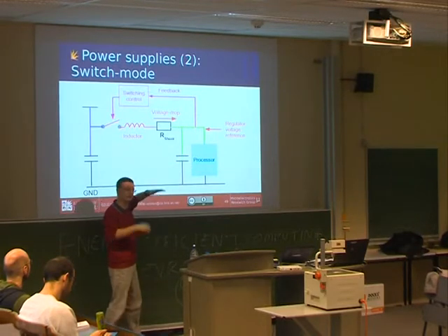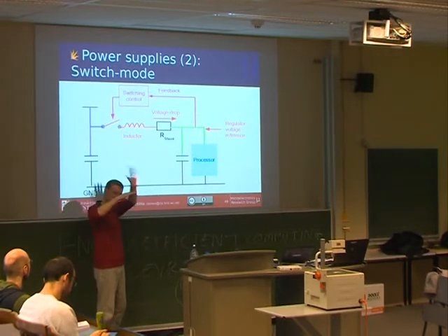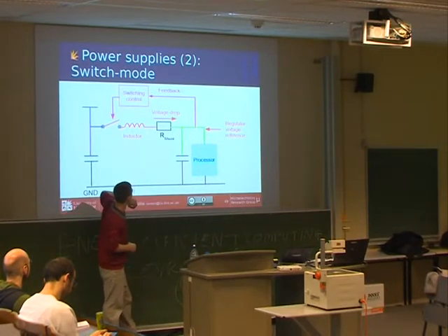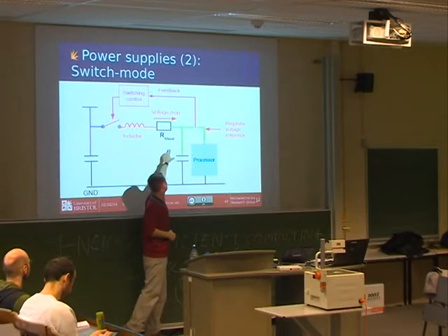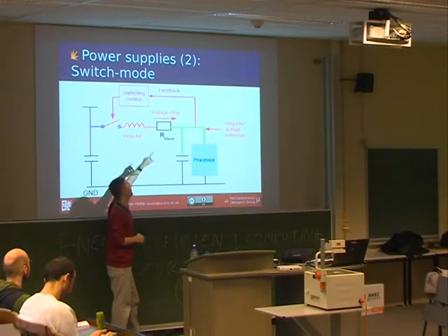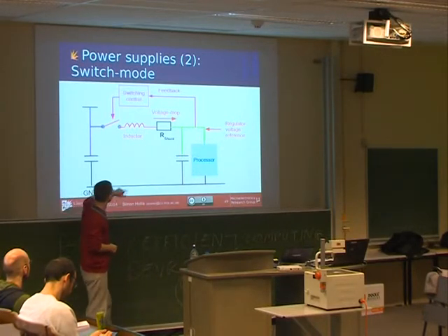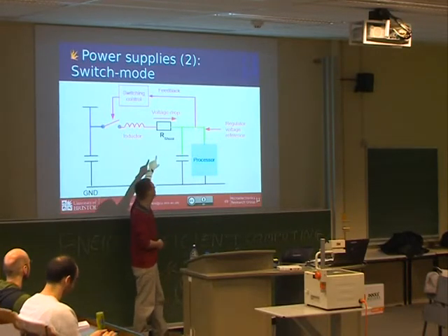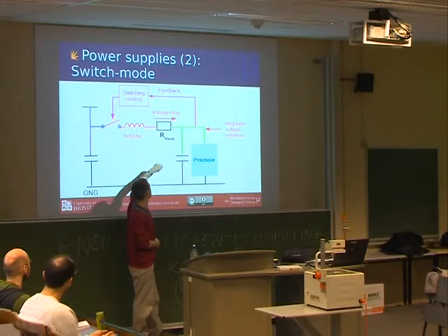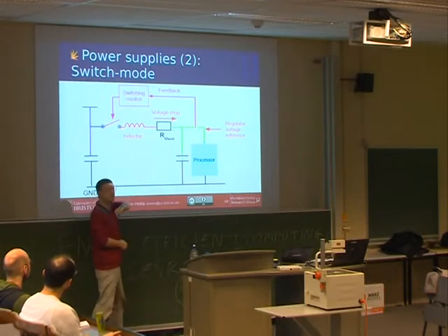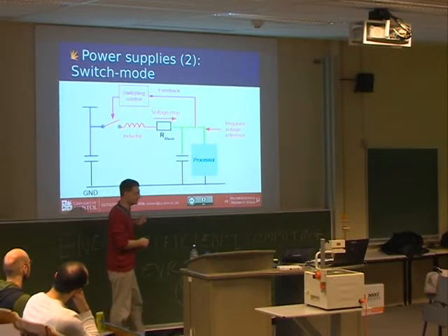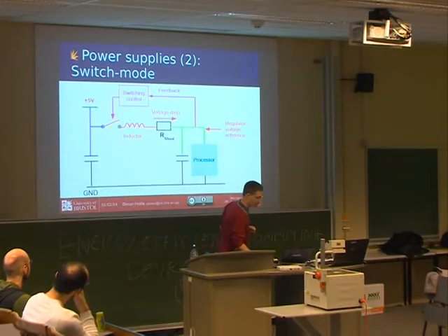And it looks at the output and says, do I need to connect the power supply again? Don't need to connect it. If the voltage is too low, it connects the power supply, if the voltage is too high, it stops. And so this thing goes up and down 100,000 times a second, and there's a measurement point where feedback comes in to decide whether to close the switch. So you put the shunt resistor in. As long as you put the shunt resistor before the feedback, and it can be in either order with the inductor, and in either order with the switch, then you will get feedback that ensures that the voltage across there is adjusted for automatically. So what that would look like in the same example, is 5 volts goes in.